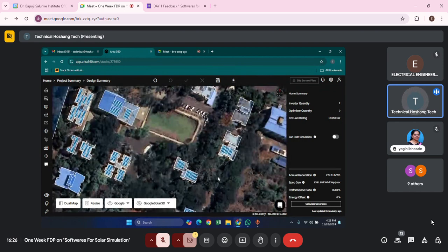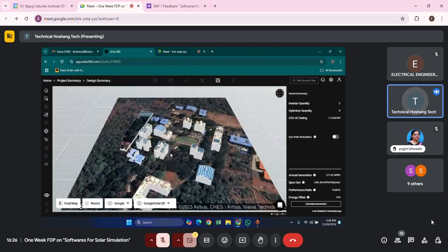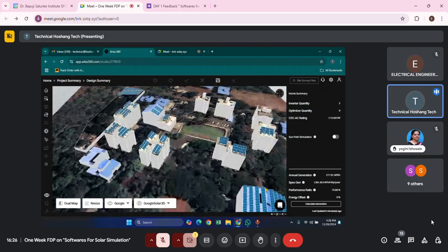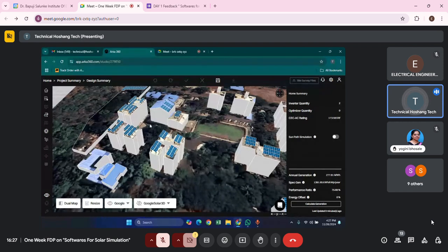The thing is, while designing the solar plants, the angle, if you see, is also not so good and properly designed, north side up, south side. So this building is almost useful for us. So these panels will generate in the early morning because the sun rises from the east, but on the west side when the sun sets, this generation will stop. The degradation of solar intensity will start by 2 p.m. to 3 or 3:30 p.m. So we won't have a lot more generation in the evening period from all these side panels.